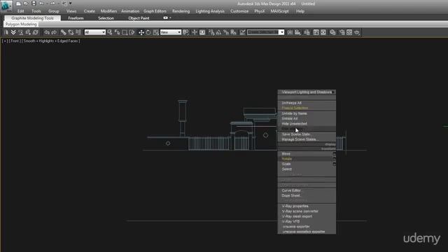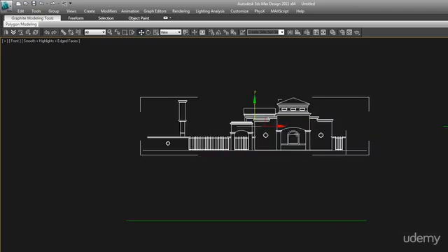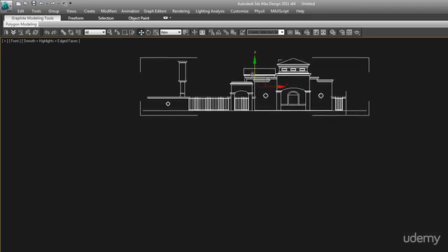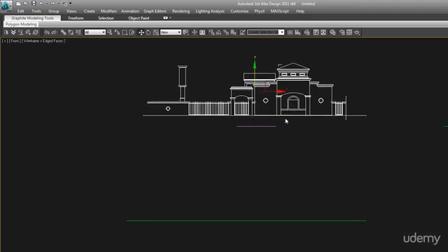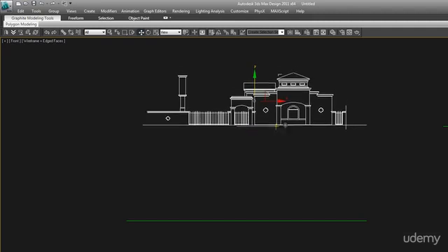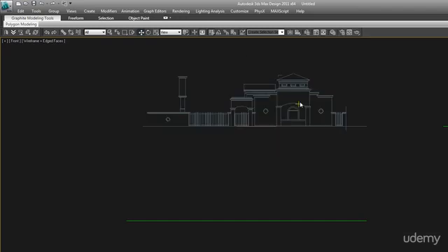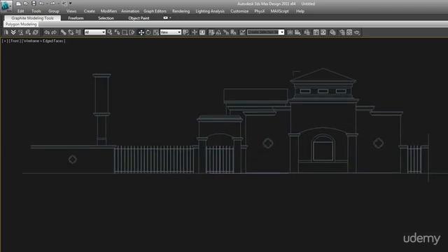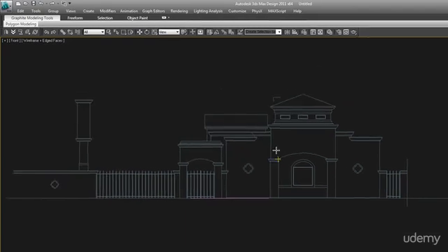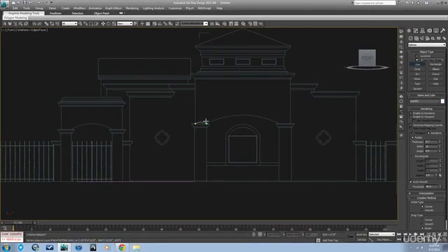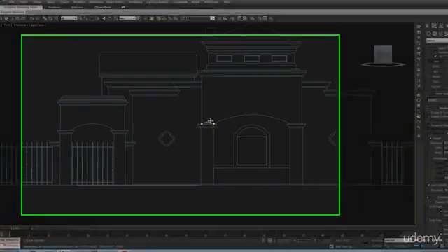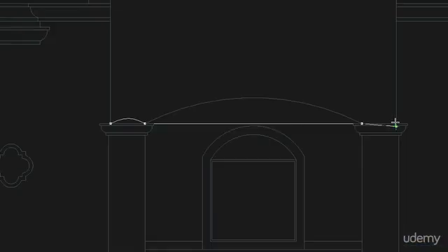And actually, you want to set this up so that the ground plane is right where we were drawing the ground before, right there. So that ground plane is at 0. Freeze it again. And then you can just start outlining all this stuff, snapping to all the vertices. Oh, that's a bad one there.